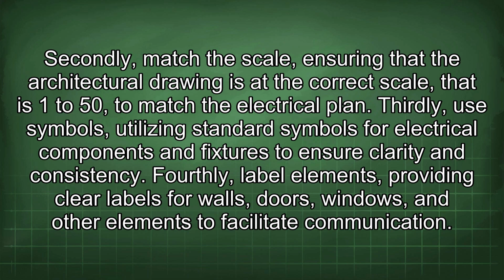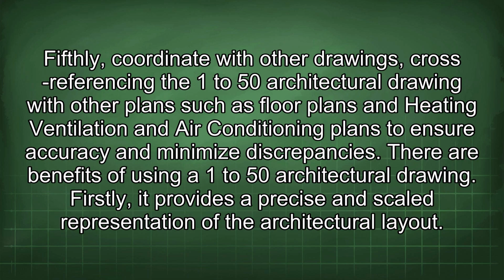Fourthly, label elements, providing clear labels for walls, doors, windows, and other elements to facilitate communication. Fifthly, coordinate with other drawings, cross-referencing the 1:50 architectural drawing with other plans such as floor plans and heating, ventilation, and air conditioning plans to ensure accuracy and minimize discrepancies.